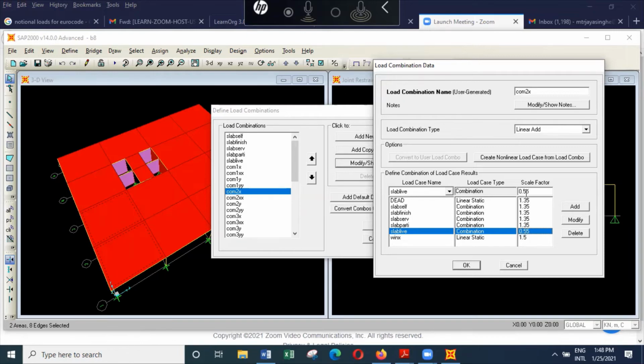In British codes as well as Eurocodes, if you look at the Eurocode national annex for England, they allow this additional component to be reduced when you are looking at the overall loads acting on the structure. When you are considering the overall effects, there's no chance that every floor in the building can be used as a dancing floor or something like that.